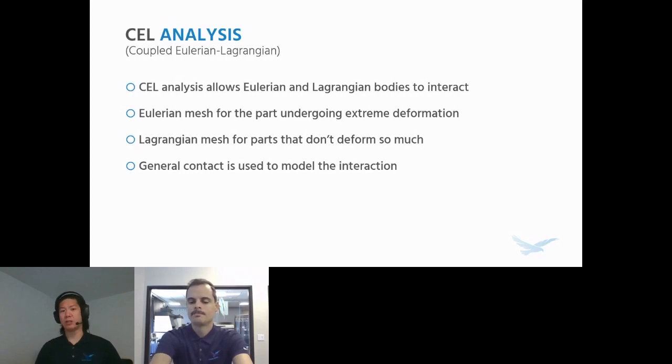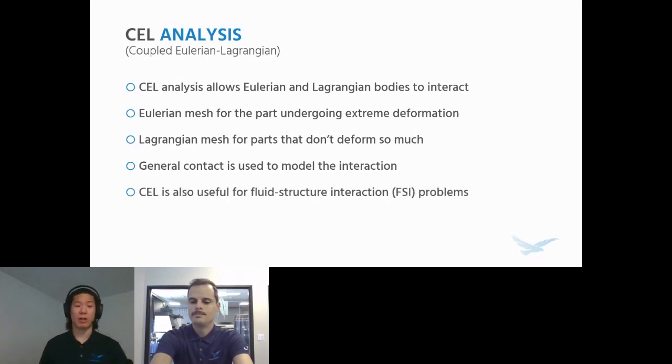This technique is also useful not just for these extreme material deformations of solids, but for fluids as well. So we use CEL a lot when we're solving fluid structure interaction problems. That Eulerian mesh can be used to represent gases and liquids.